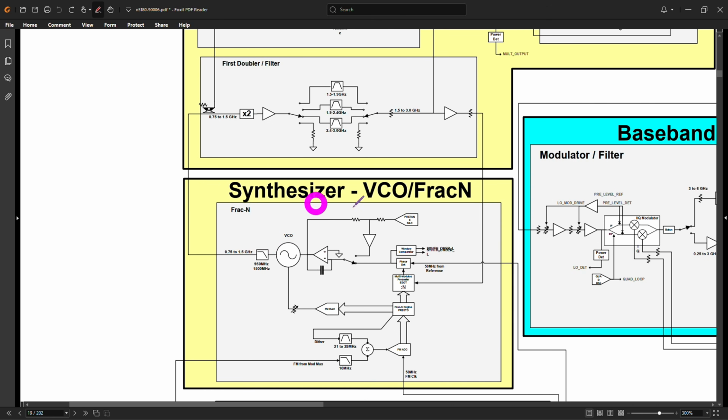So now that we have verified the filter bank and the switches and everything is working, we should turn our attention here to the bottom and change our strategy a little bit. Now, one thing that can happen to VCOs is that they can lose the ability to sustain oscillation across their entire desired tuning range. Typically speaking, this happens on the upper frequency ranges, not on the lower, but it can happen either way depending on what goes wrong.